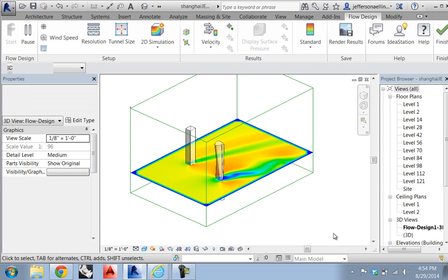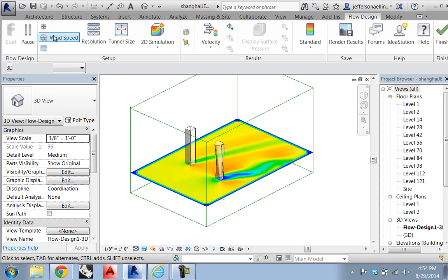So that'll show you your wind direction, wind speed, pretty clear too. Again, you can get this information from your wind roses as you move out concentrically in your wind roses. It should tell you what the wind speeds are, and I think probably in miles per hour. You need to convert that to feet per second, so you can input the data correctly.